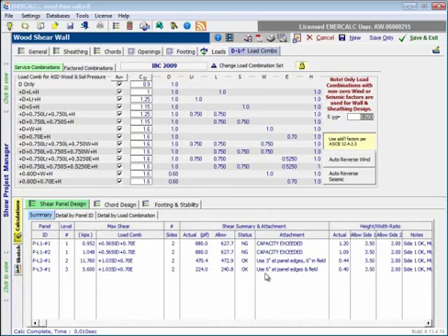So notice that the shear accumulates from the top down. At level 3, which is the topmost panel, we can use fasteners at 6 inches on center at the edges and in the field. When we get down to level 2, we need fastener spacing a little bit closer. And then my 2 panels at the bottom are partially hurt by the fact that I've added a penetration and also are accumulating more shear, so their capacity is just exceeded at this point.